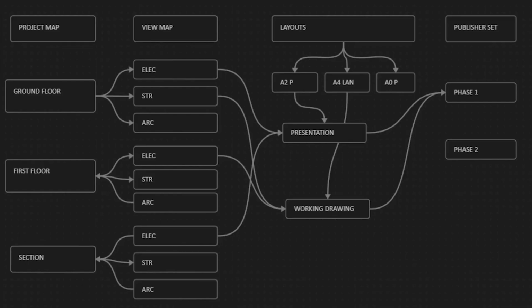Next thing, we set the master layouts for different sheets, the title blocks, you can call it, and created a layout and placed each of the drawings into the layouts. So one of the methods was manually creating individual layouts. Another method that you saw right now was automating the whole process by using the place drawing option, where if you click on a folder, click on the place drawing option, it automatically creates multiple drawings for you. So go through the process. This is how we set up the layouts or the sheets.